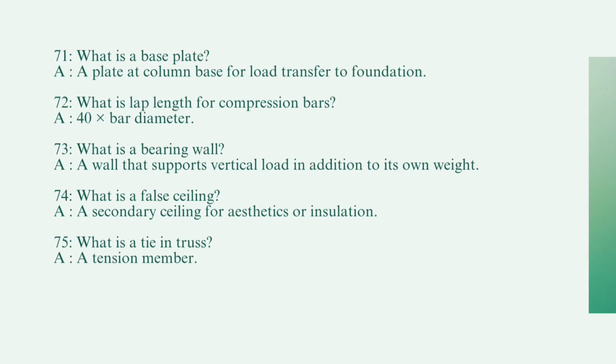Question number 71, what is a base plate? A plate at a column base for the load transfer to the foundation is called as a base plate. Next, what is a lap length for the compression bars? It is 40 into the bar diameter.